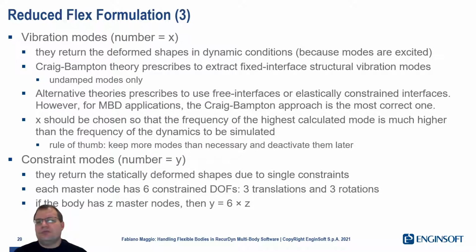How many frequencies should we keep in this modal analysis? This is the big question. But in practice, it's good to keep a number of frequencies big enough to have the highest frequency exceeding the highest frequency that we expect in the simulation.